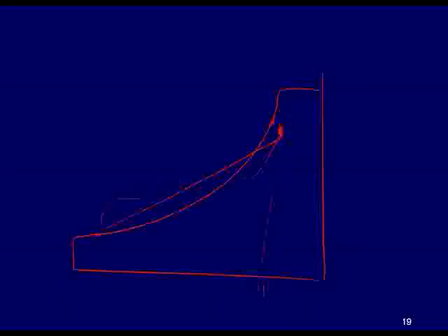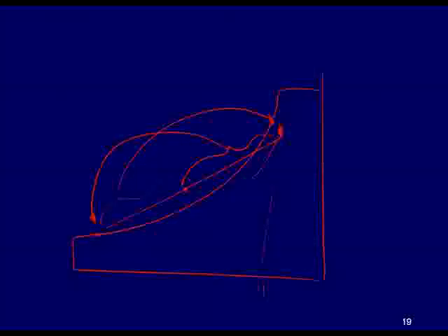31 degrees, fairly warm air, is mixed with 10 degree saturated air. This I was talking about earlier. If we mix them 1 and 1, 50%, then the mixture would fall, well, this distance would be proportional to stream 1, and this distance would be proportional to the mass of stream 2, and you would land halfway in between, since it's a 50-50 mixture, 1 kilogram of one, 1 kilogram of the other.